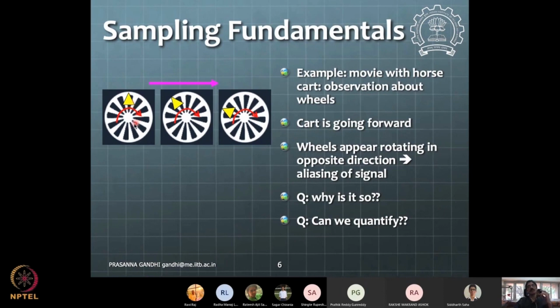So there is also a sense of sampling speed. Say the wheel has some RPM, or frequency of motion omega 0. If I sample 2 samples per cycle, so for one cycle I take 2 samples, then I'll have one pointer here and another pointer here, and I'll have some kind of lossy situation. But if I take more than 2, then I'll immediately start seeing the motion. So what we are talking about is the number of frames per revolution. We are not talking in terms of time, per second, so you don't get confused.